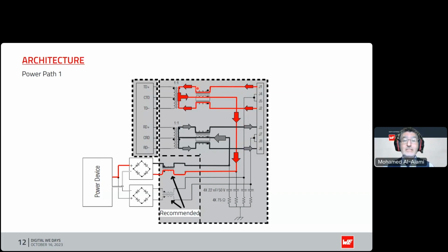So it basically looks like a wire carrying the current. I need to keep that common mode choke there to do common mode noise rejection for the data noise coming on the data pairs that we were showing on the previous slide. So that's something very important to keep in the back of the mind.